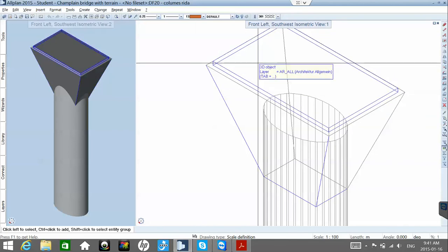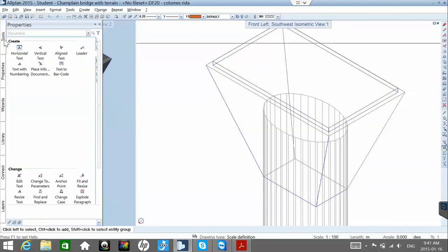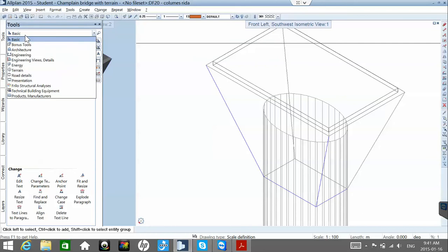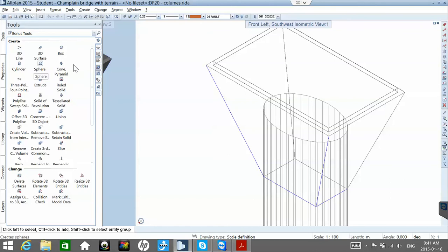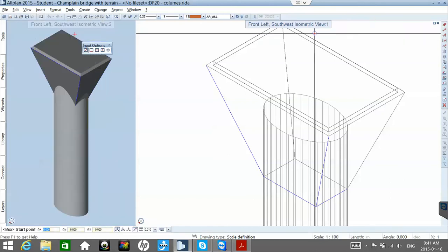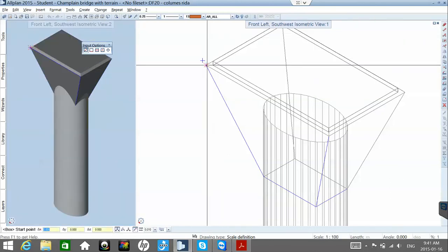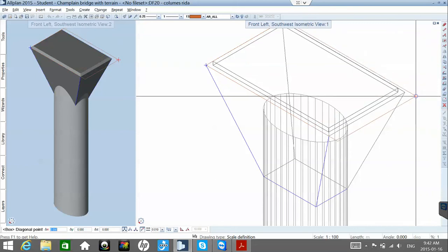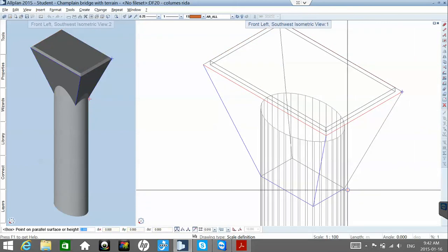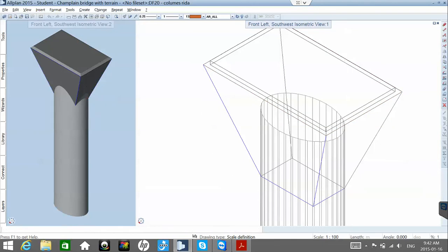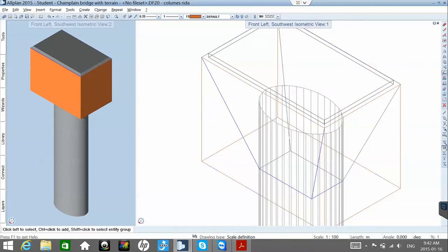Well, now that you drew, it's pretty easy. We can do a trick on this. We have many options in doing things like this. One easy option would be this one. Really easy. We'll go to bonus tools, 3D modeling, we select the box, and okay, we'll use that brown. So what I'm going to do now is create this box. So this is the top side, and then for the height I'll extend up until here. And now this is a filled box.